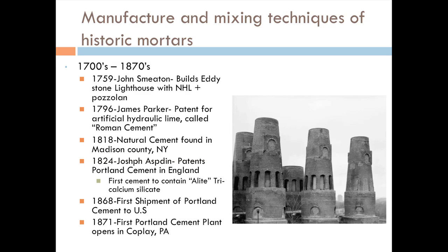But what they had to look for was limestone that, when burned, did not slake. Nothing happened. And they found that if they ground it down to a fine enough powder with millstones, it would get hard as a rock within anywhere from 20 minutes to maybe 2 hours.